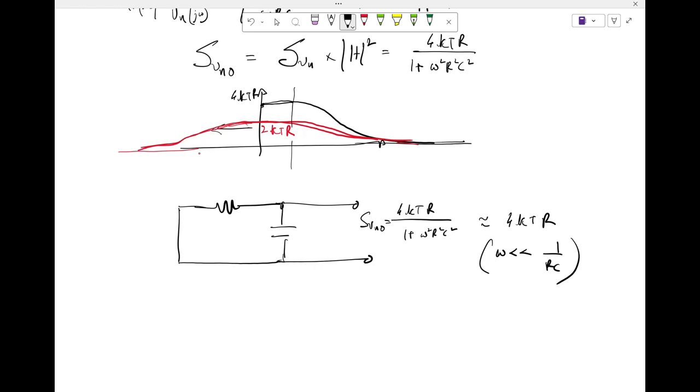Right. We should not consider only noise, because ultimately the whole purpose of designing a circuit is to process the signal, and noise is something that comes along with it. So we have to ensure that the noise does not play spoil sport. But you cannot unilaterally consider noise always. You have to consider the effect of both signal and noise. So essentially, we have to talk about signal to noise ratio.